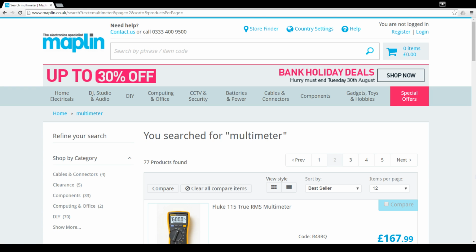So I'll do JH Open Source's second question about the 555 timer, but for now, let's just cover the capacitor question about what type of capacitors should you use where. Well, typically electrolytic capacitors are normally used in power supplies, since they've got such a high voltage sometimes and quite a high capacitance as well. But they can only really deal with positive voltages, so you can't use them directly on AC, you have to rectify it first, hence why they're most often used in power supplies.